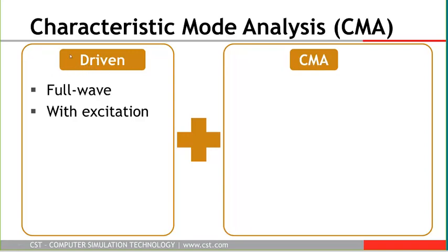When we speak about driven simulation, this is what we understand as a full wave technique, so there is no approximation to Maxwell equations, and we have some kind of excitation, whether it's a port, a mode on a transmission line, or a plane wave. The important thing is that we have some kind of excitation.